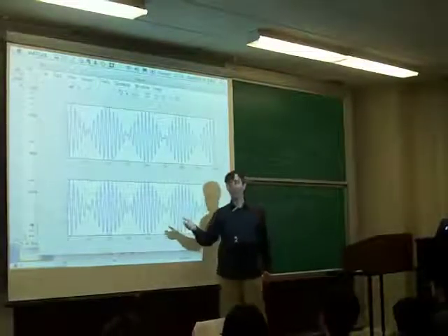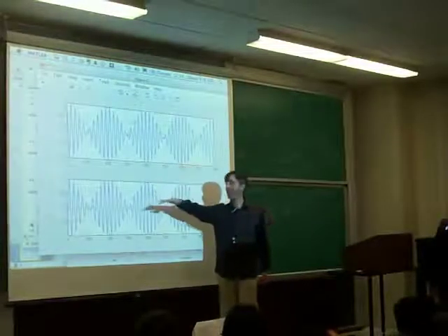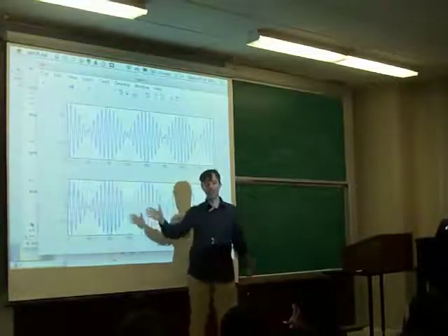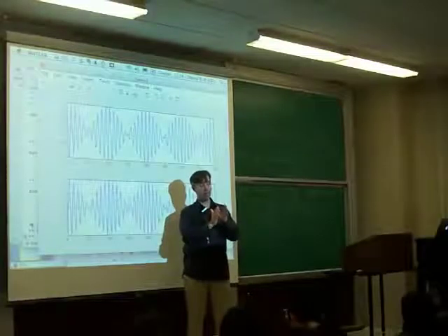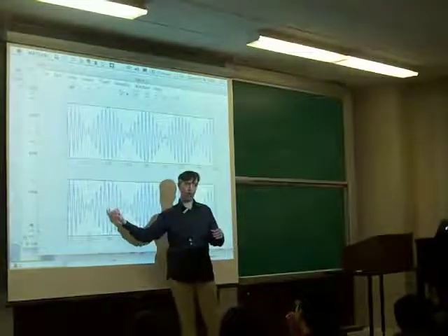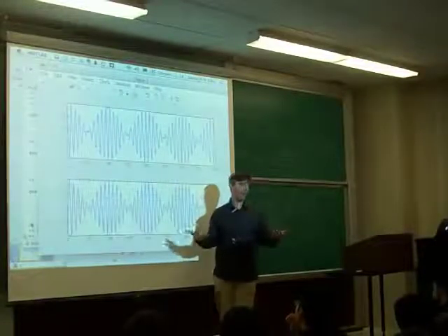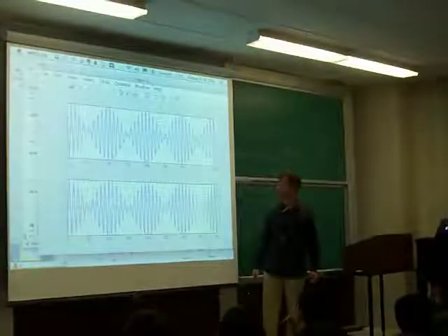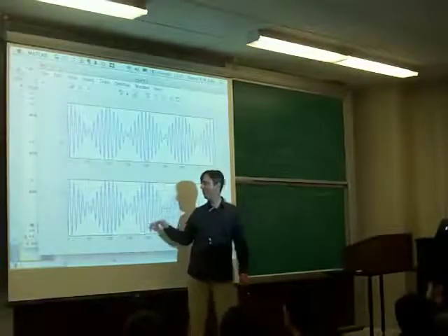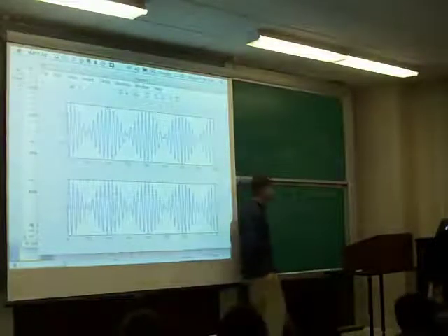And in that case, the system goes through the atmosphere. The atmosphere might have different gains at different frequencies, including different phase shifts, as long as they're relatively constant within the bandwidth of the carrier, things are okay. If the phase or the amplitude changes too rapidly, even within the 10 kilohertz of modulation bandwidth you're putting on, then you get a distorted signal and you hear bad, weird radio reception distortion. But in other cases, it may be that the envelope is not what you're getting at. You're interested in the fine structure, and then suddenly you care more about the phase delay. So those are the two things we distinguish.